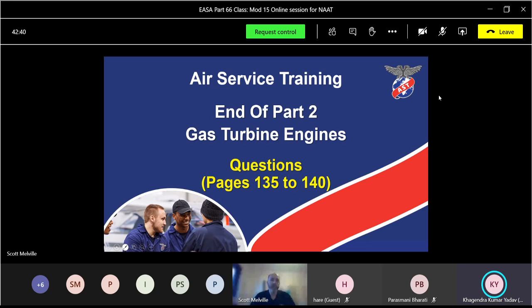Whenever we do maintenance. Yeah, specifically to control. So what does that mean? We have to put the setting as, expand a bit more. Yet we have to achieve the basic setting after the maintenance of any control. Yeah, it's if you've disconnected any control from the engine, as you quite said, we've got to set it up to specific settings, either adjusting the length or the radius, to adjust it. And it must be duplicate checks because it's very, very crucial.